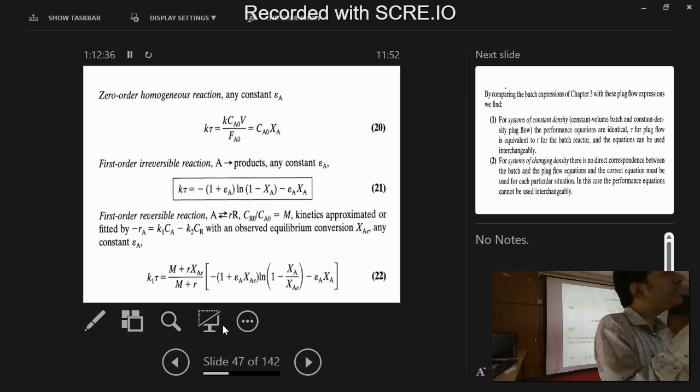Okay. So fundamentally, batch reactor is unsteady state, whereas flow reactors, both CSTR and plug flow, are steady state reactors. Fine. Now, in the flow reactors you have tau coming into the picture, but for the batch, t comes into the picture. For the plug flow, there will be only lateral mixing, there will not be any axial mixing. But for CSTR, there is back mixing, overtaking, over mixing. So different names: back mix reactor, mixed reactor, continuous stirred tank reactor, continuous flow stirred tank reactor. Whereas for the plug flow: slug flow, piston flow.